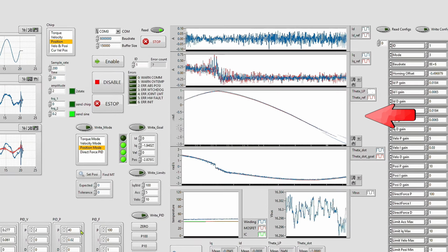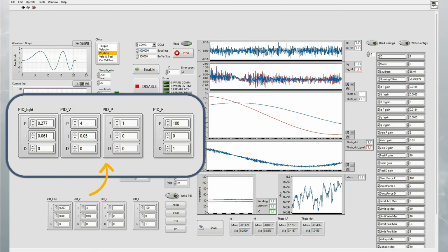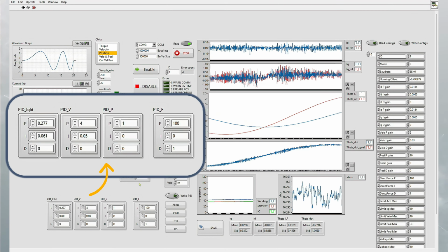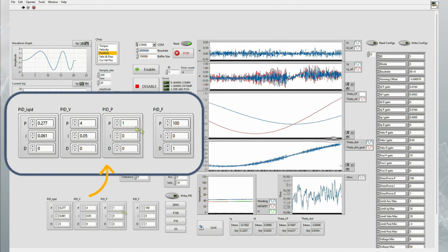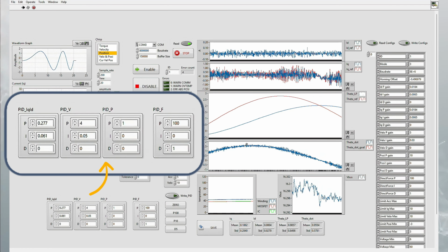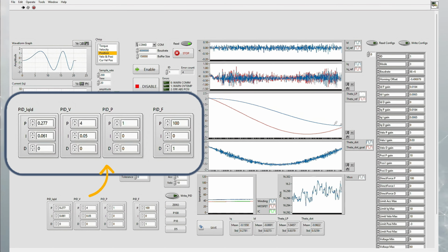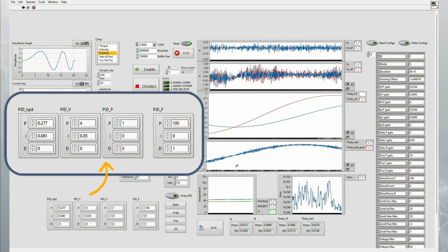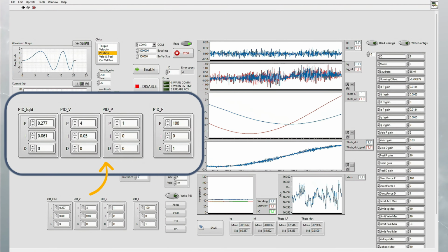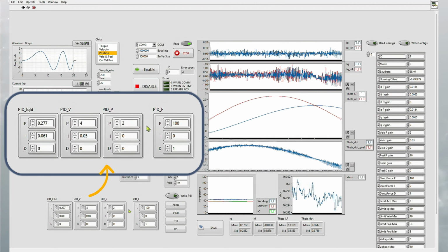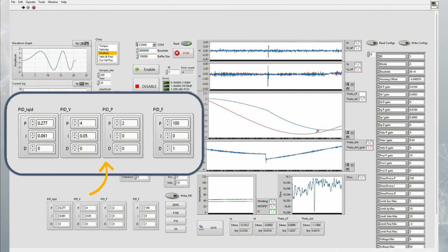A practical workflow for position tuning. Step 1. Establishing the baseline. Start with your pre-tuned velocity loop parameters. Initialize your outer position P gains at a low baseline value. Ensure the position integral I and derivative D gains are kept at 0 to prevent low frequency windup or sluggishness when approaching the target coordinate.